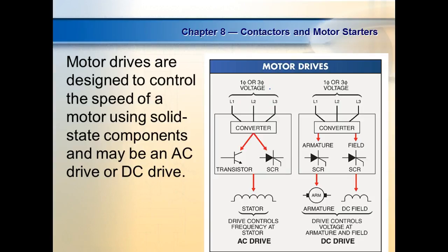If you just change the frequency on the motor, raise the frequency, the motor would stall. Lower the frequency, the motor would burn up. So you just can't play around with the frequency on an induction motor. You have to vary the voltage. If you raise the frequency, you have to raise the voltage by the same ratio. If you lower the frequency, you have to lower the voltage. Which is pretty important because when you program a variable frequency drive, that's what you have to tell it. You have to tell it what voltage the motor runs on and what frequency it runs on, and then it'll calculate that voltage to frequency ratio. It's really easy.